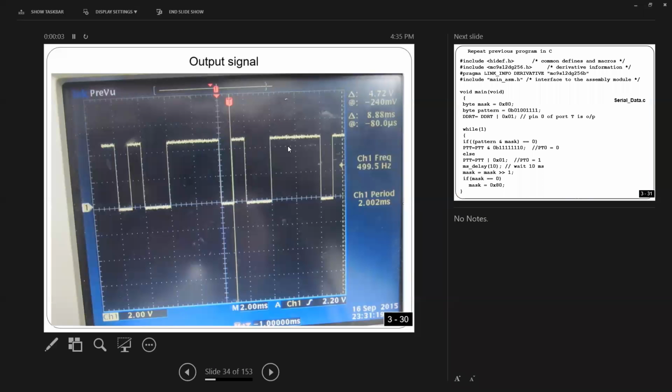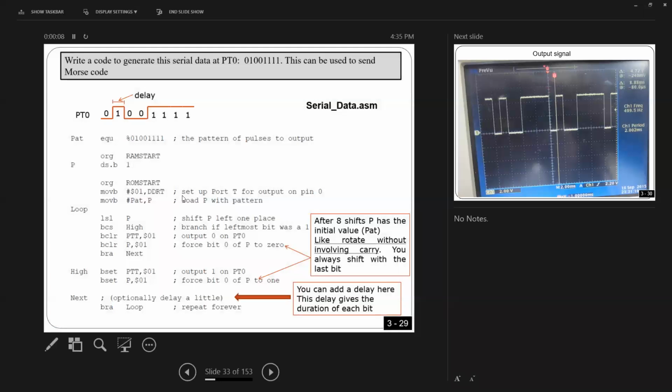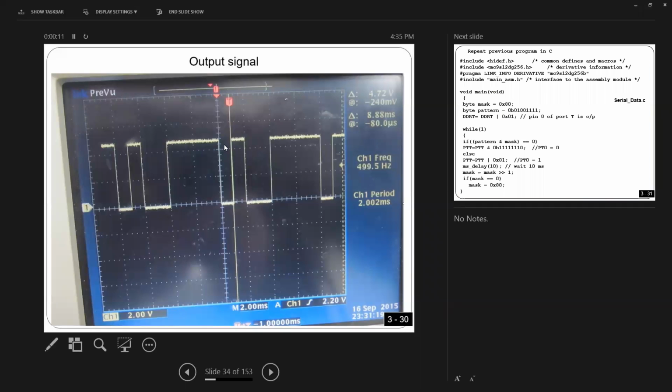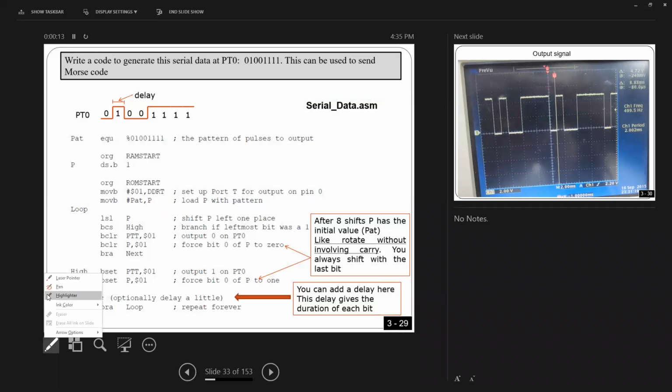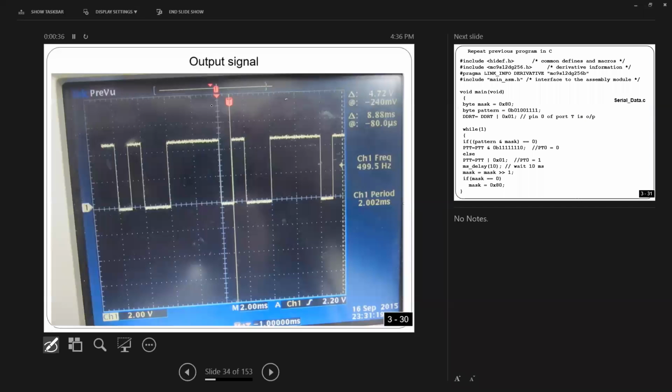Okay, so as I told you guys last time, serial communication means where this is the microcontroller. We have one pin here. If you connect the scope to this pin, you can see the serial data. Serial means every certain time, like 10 millisecond, 5 millisecond, whatever it is, you are going to get 1 bit, right? So if you connect the scope here, and that's what you should do in the next lab, you should see something like that. This is serial data.